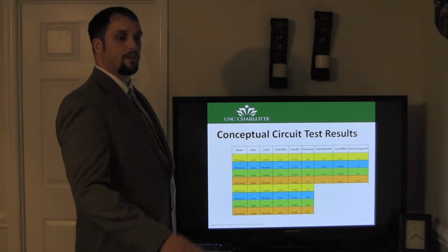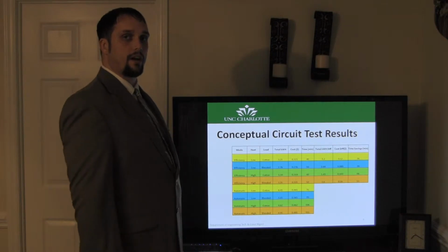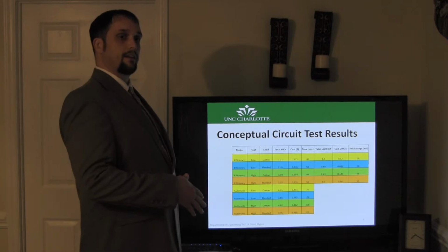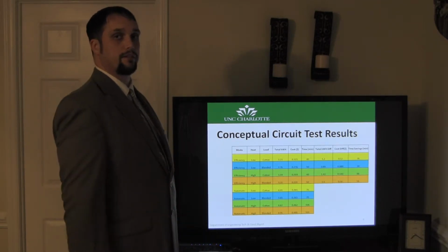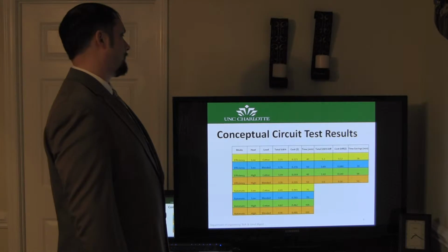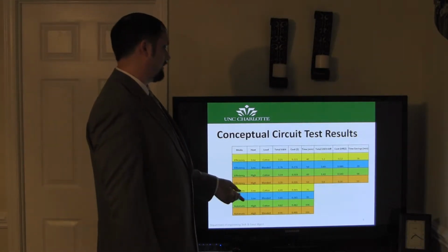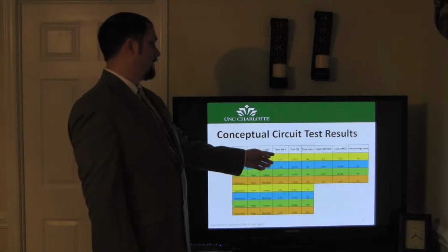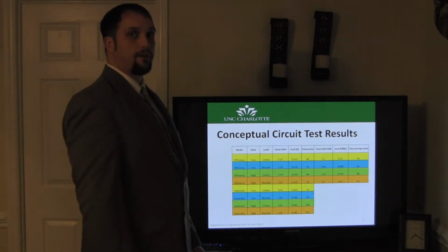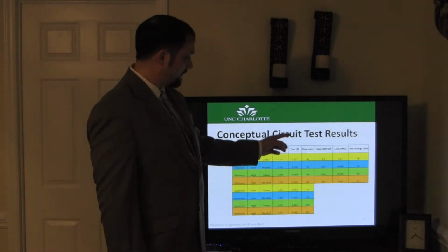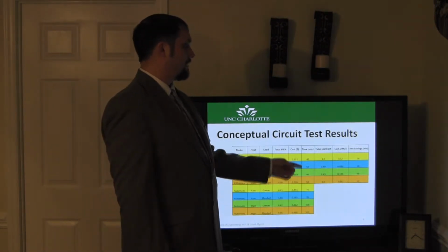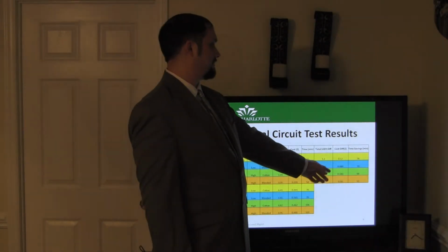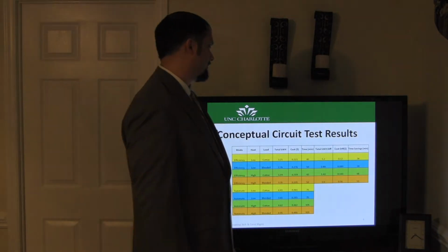That's the automatic setting that comes with the dryer, and efficiency is the conceptual circuit running the drying cycle. We have 2 different heats, high heat and low heat, and 2 different loads, cotton and blended. We talked about that before. We calculated the total kilowatt hours for the dryer cycles, the cost of the cycles, and also the time, and then the total kilowatt difference, the cost difference, and the time savings.